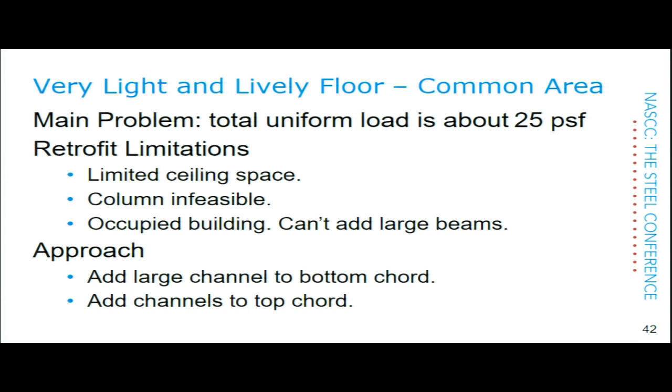So our approach here is to just add a large cold-formed channel to the underside of the bottom chord, and add a couple of heavy shorter channels to the top chord and just screw them in there to get more mass and stiffness.